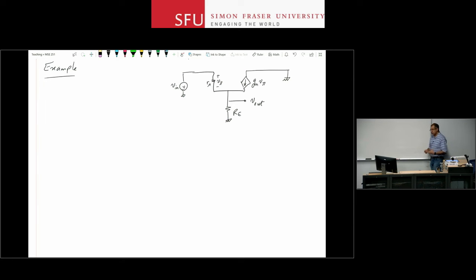And we do this with nodes that are used a lot in your circuit. In this case, ground is usually one of them. You have a lot of ground connections throughout your circuit. But you also have connections to, let's say, positive power supplies or negative power supplies, as we will see later on in this course. If you have, let's say, 10 connections to the positive power supply, I don't go and draw a line and connect all those loops to the positive power supply. I choose a label and I say, this is VCC, VCC, VCC, VCC, and so on and so forth.